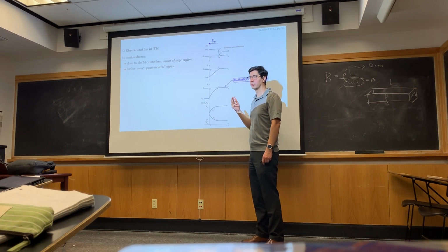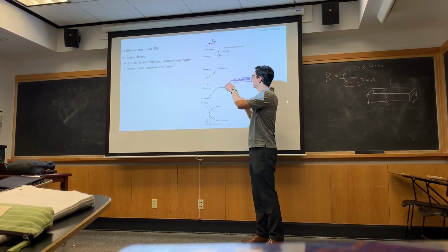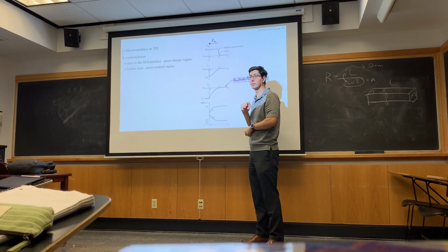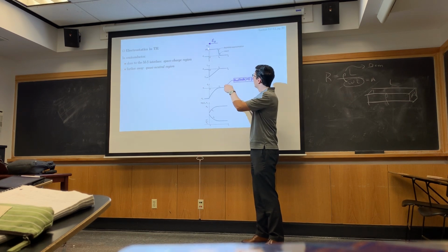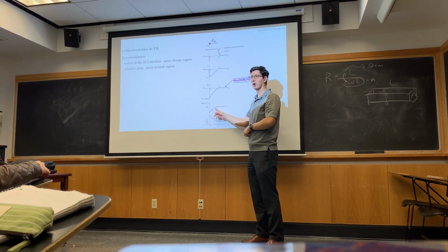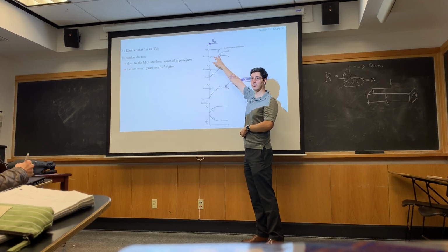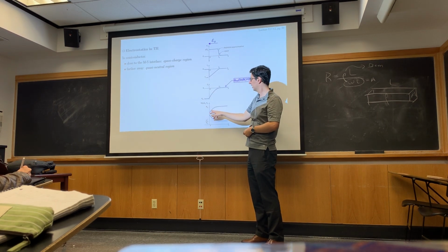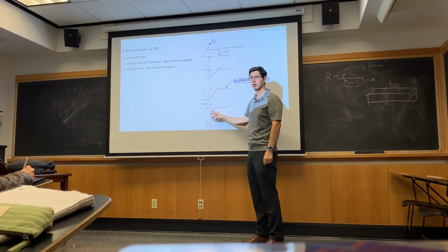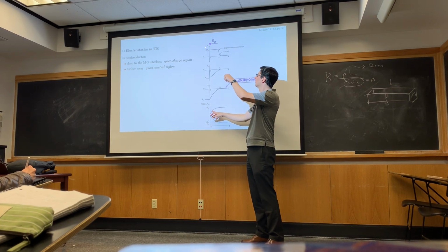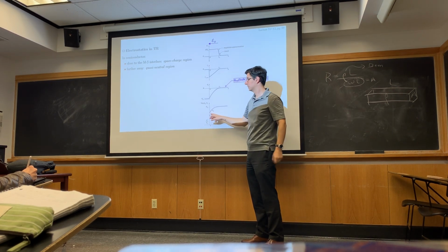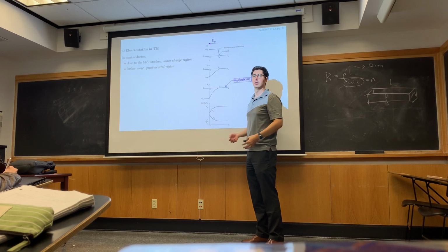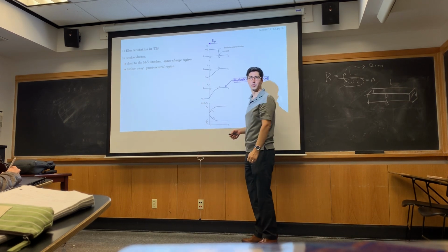Overall, I should point out the depletion region is definitely an approximation. Well, how do we know that? Well, we put in this square profile, and what do we get out? Right? So okay, look at the dashed line. That's the depletion approximation. Is this a perfect square? No, this is assuming all my carriers are depleted. Well, this doesn't look like a perfect square to me.